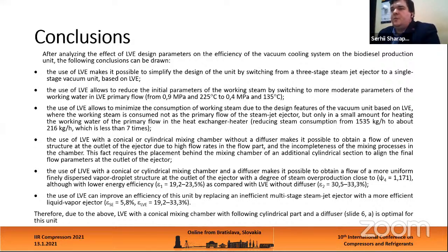The use of liquid vapor ejector allowed to reduce the initial parameters of the working flow steam by switching to more moderate parameters of the working water in liquid vapor ejector primary flow, from 0.9 megapascals and 225 degrees Celsius to 0.4 megapascals and 135 degrees Celsius.